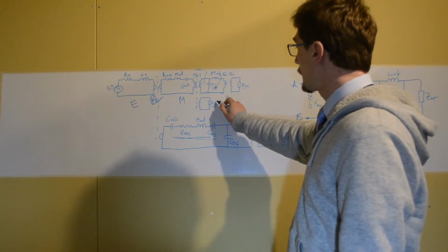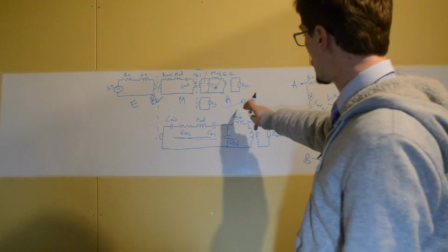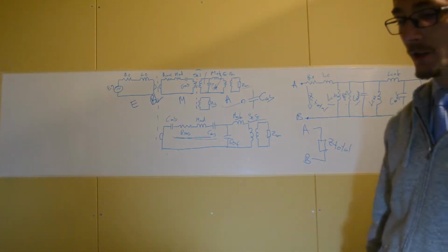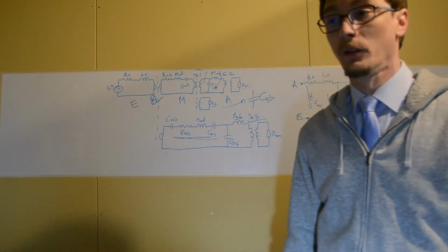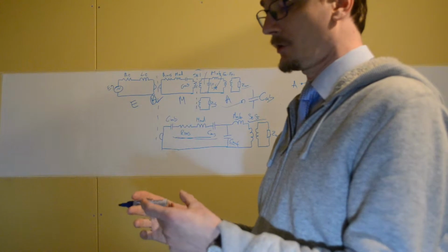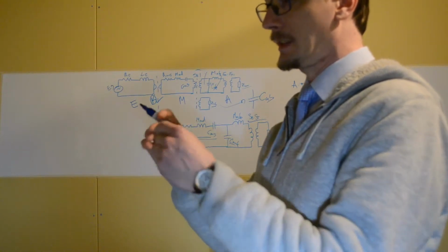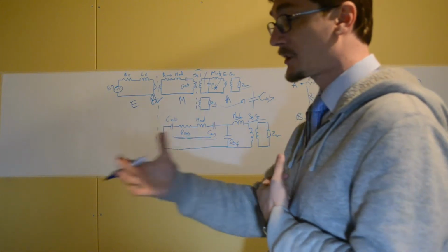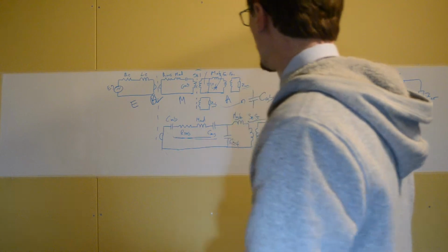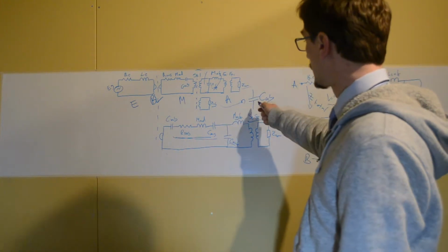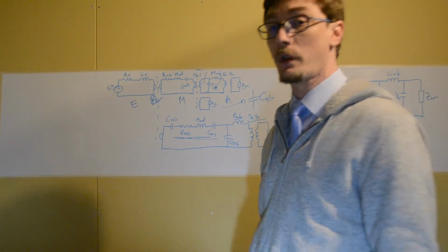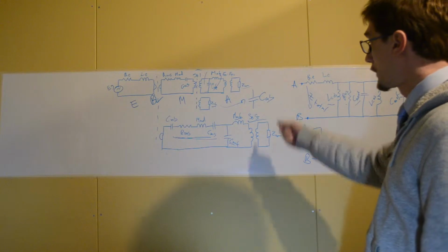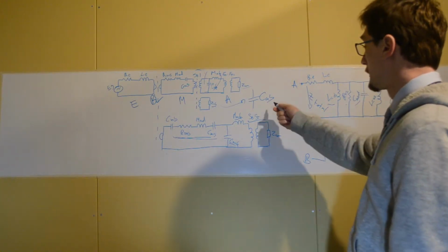The back of the diaphragm, for now, just for our impedance calculation, we'll just mark it as compliance. So we'll just put it as CAB. Of course, depending on its geometry, the back chamber is like a disc, like a hockey puck, if you think about it, right? The length that extends towards the back is shorter than the actual diameter, so because of that, it's not exactly a compliance. Plus, a lot of the drivers will have some sort of sound absorbing material inside that chamber, which again will complicate this network here. But for now, let's just keep it like this.